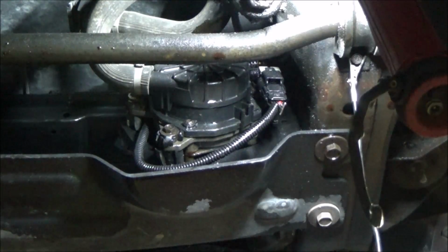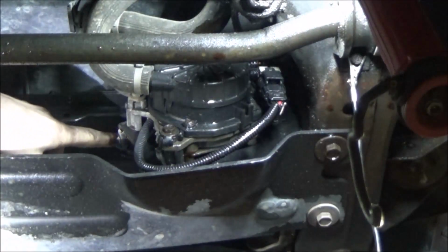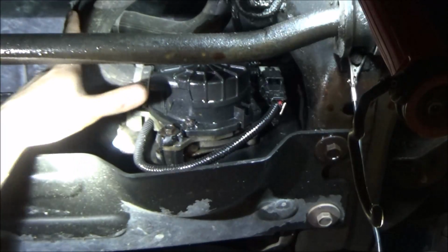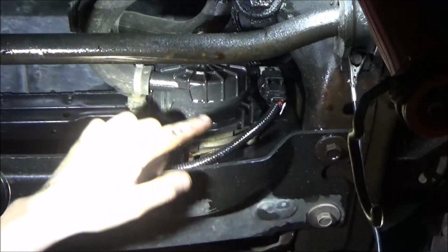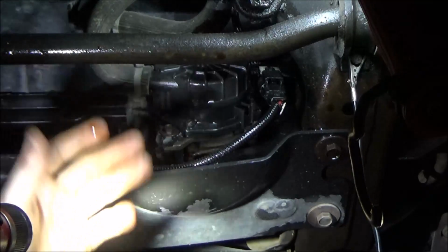The fix for this vehicle, guys, is going to be to replace this air pump motor. It's also going to need this air pump solenoid. And I'm fairly certain that this whole unit probably comes as an assembly. And really, we need to tell this guy about this transmission fluid leak because it needs to be taken care of. That's probably what took this pump out in the first place. Wow, I just touched it and it stopped.